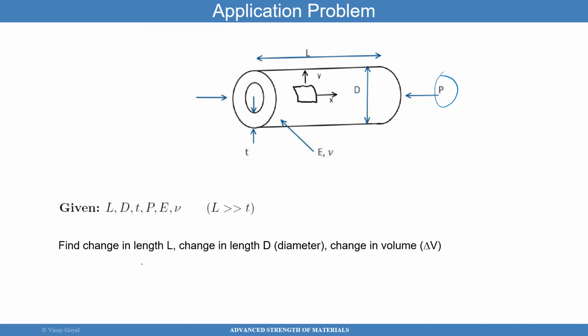Well, one of the things we're going to require is if I apply a load to a cross section that has cross sectional area A, I can calculate stress. So how to calculate the area, because that's going to become important. One way to do it for thin vessels, you can calculate the area that's shaded there by taking the mean diameter basically.